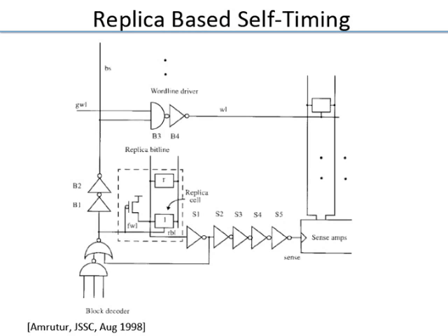Then what do we need an SRAM for that? Then how do we activate that SRAM? So it's a never-ending problem, right? So to deal with that, what is done is basically for the replica, you do away with the SRAM, but you have a simple inverter. But then the replica bit line voltage should be a full swing. So you still want to have the tracking.